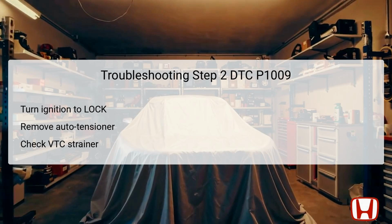Once the tensioner is out, proceed to remove the VTC strainer itself. Inspect the strainer for any signs of clogging or debris that could be obstructing oil flow. If the VTC strainer is clogged, it will need cleaning, and it is recommended to replace the engine oil filter and engine oil to ensure the system has clean fluid.